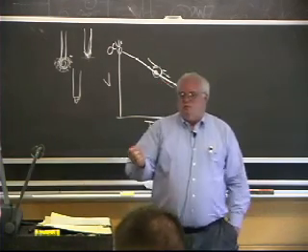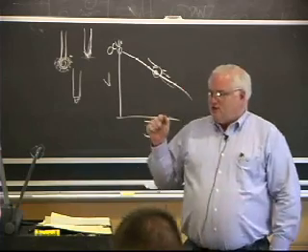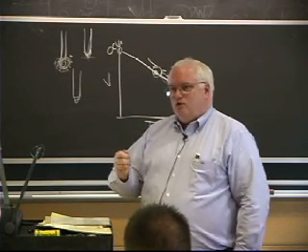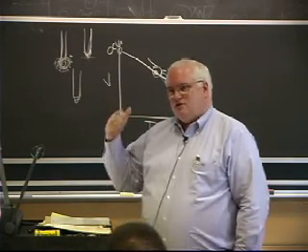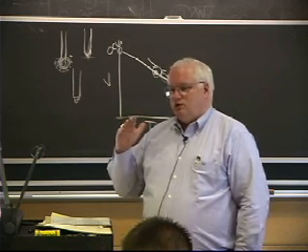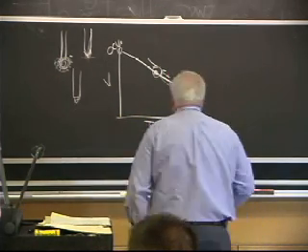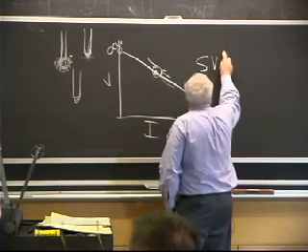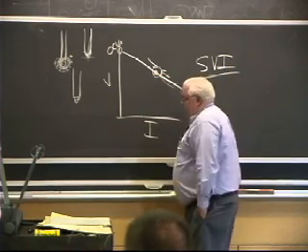In fact, that's what you do. That's why you can have this kind of constant wire feed, and you can have a human whose motion is not perfect because there's a self-stabilization, provided you have the right voltage slope. So typical, in the old days, they used to have slope voltage inductance, SVI power supplies.